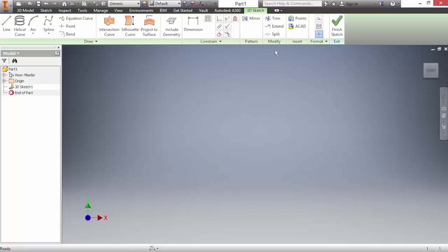We also have the ability to import X, Y, Z points, an AutoCAD file, as well as use construction geometry and driven dimensions. Now, as far as the unique tools that are here, we have a Helical Curve command, which allows us to build a helical curve based on points. It's usually a good idea to have at least one starting point on your screen, such as the origin point that might be projected, or the end of some other geometry that you're including.